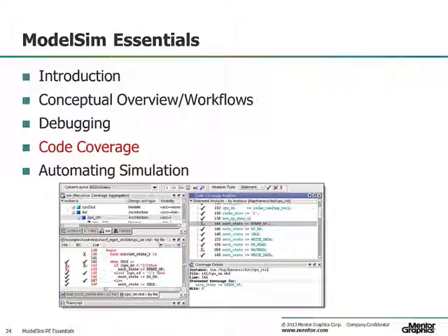And then we automatically extract coverage information as you're simulating your design, and not only extract that information, but allow you to view the results and easily identify what you have to actually exercise in order to stimulate that line of code. So as you can see for this one example here in this screenshot, there is a state machine start op state that has not yet been exercised by your test bench. In this way, you can easily identify coverage holes and analyze what you need to do to accomplish stimulating that area of your design, in this case a state machine.